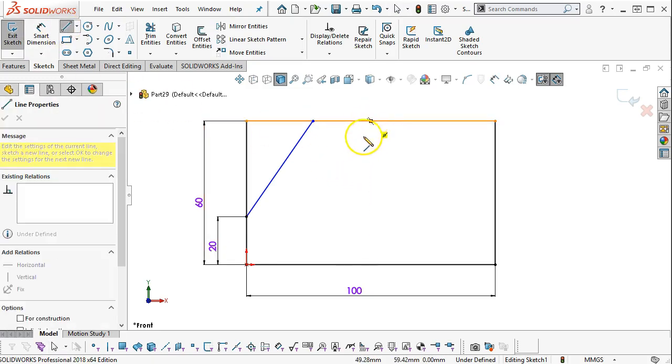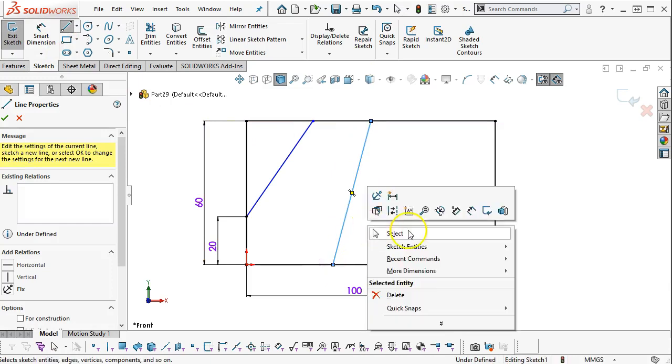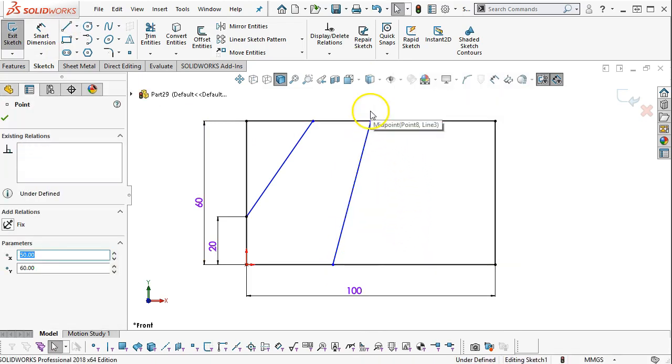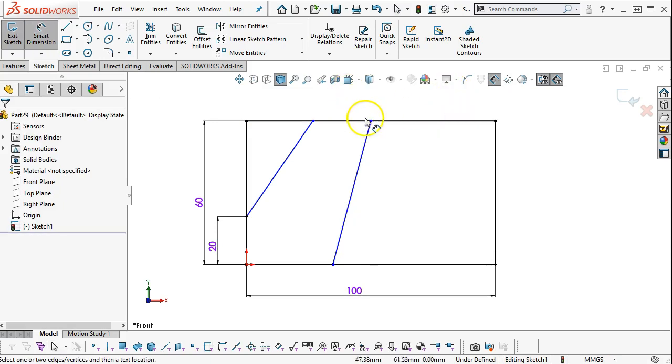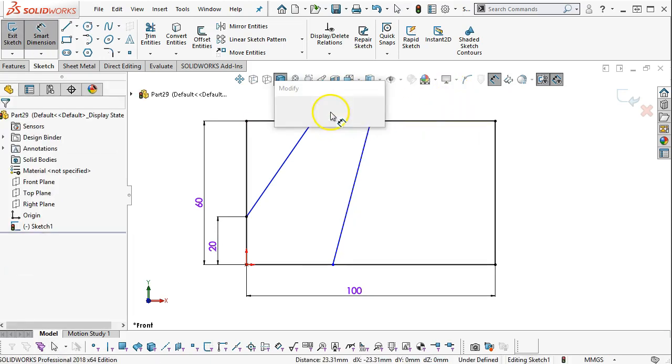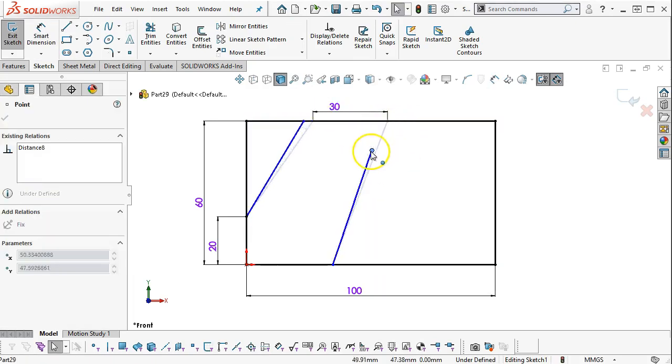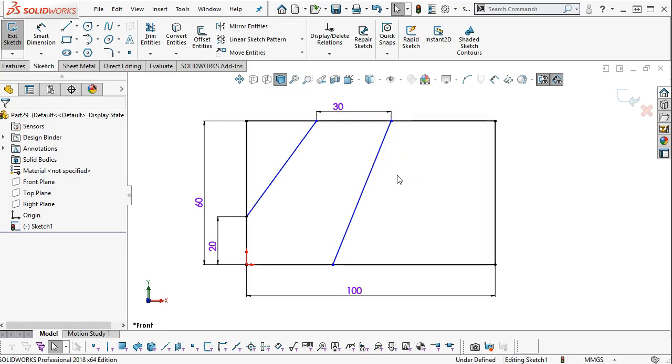All right, so let's get a few more lines in. Grab the midpoint, so that wasn't really what I wanted. So we'll get rid of the midpoint. 30 millimeters. And the thing to watch when I get rid of the midpoint is, did it stay coincident? Is it going to move off of that point? Which, yes, it does. So we'll put it back coincident. And then the base goes to 44.